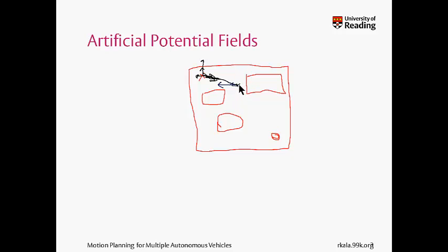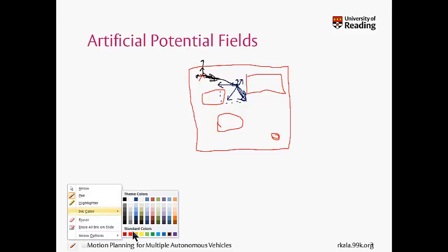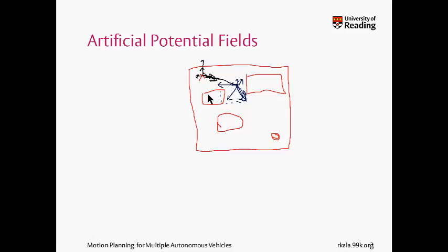It is not that strong out here. It sends a small repulsion force. It will be a very small repulsion force out here, and the goal attracts using some force like this. So the overall motion will be the vector addition of all these, which means the direction in which the robot would be traveling will be like this over here, and that is how the robot will basically move.